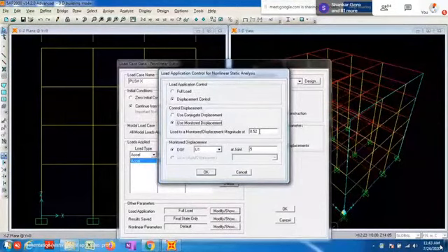We can change this. Suppose we are performing a displacement based method, what is called the displacement coefficient method. Then estimate the target displacement and push the structure up to that value. If the user has the value, that is, up to what level the structure should be pushed, give the value as input here. Otherwise, the software automatically gives the 4%. Then in the U1 direction, X direction, pushover.